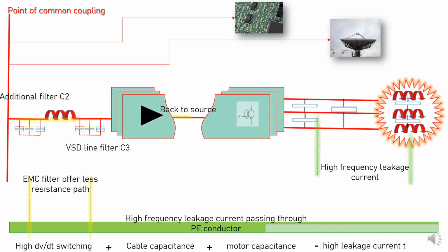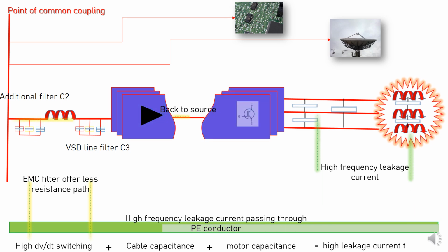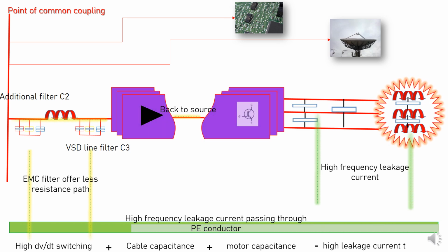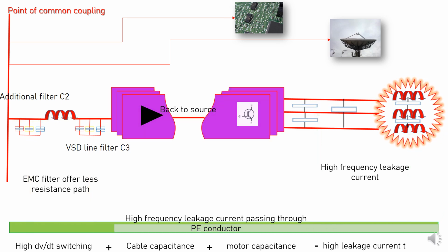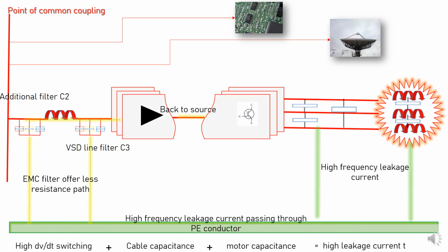In this case, the most important precaution is that your filter must be tuned according to the frequency of the leakage current. This is the most important point, and that is why we normally procure this line filter from the OEM only, because they have the best calculation of how much leakage current will be flowing, and at what frequency. So this is how we can avoid it.